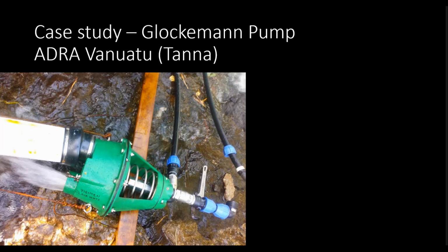So as you hopefully were able to hear and maybe see some of the pictures or a little bit delayed movie on your screen, but at least hear the audio, as the water comes in through the drive pipe here and enters the main pump chamber, it actually compresses that black thing, the diaphragm, and compresses that spring, and then as the spring rebounds, it creates the push motion through the delivery pipe here, and then you've got the same release idea, similar to what we saw with the ram pumps, occurring here.